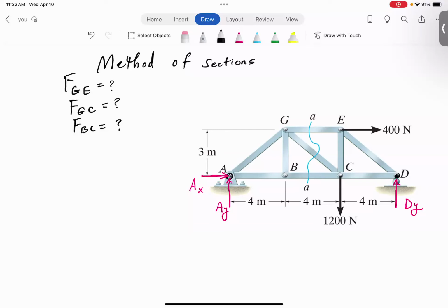Rigid body equilibrium, that you could easily take moment about. If you balance the forces in the X direction, sum of the forces in X equals 0, right? What do we get? AX has to change direction and be equal to this 400, right? Because this 400 has to balance the direction of what? To the left. Basic equation, just equilibrium in the X direction.